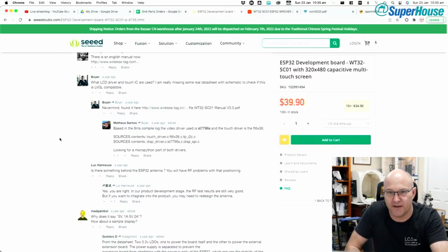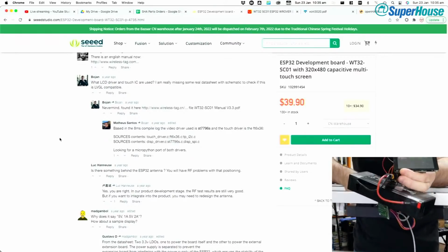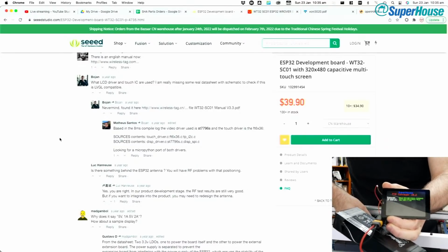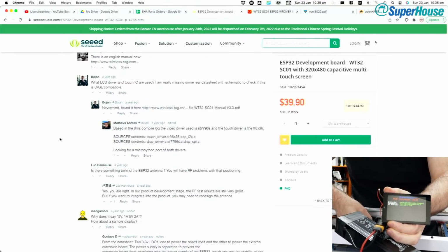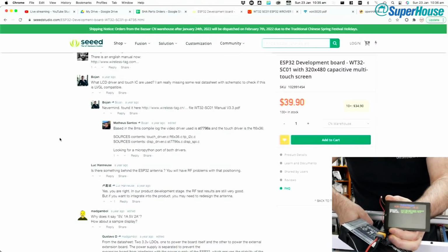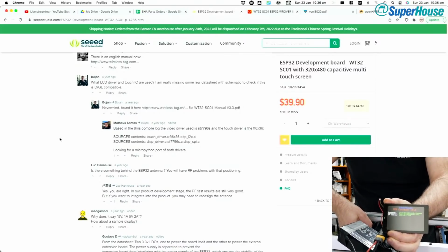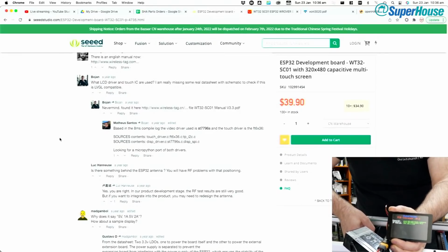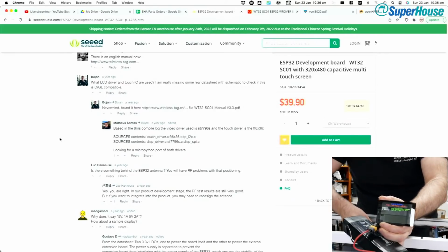I don't know if you're going to be able to see this at all, but yeah, that display has now woken up and it said that it is the Superhouse conveyor controller. It's connected to Wi-Fi. It's telling us its IP address. It has subscribed to MQTT. So I can actually send G-code commands as MQTT messages, and this responds.